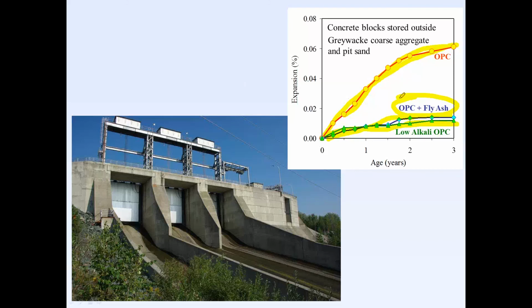We went to revisit this structure last year. It's 40 years old, and after 40 years, it's standing up very well. Not a sign of ASR, no cracking on the structure, well, apart from minor cracking that's not really attributed to alkali silica reaction. And it would seem that fly ash has proven itself over the past 40 years as an effective preventive in this case here.